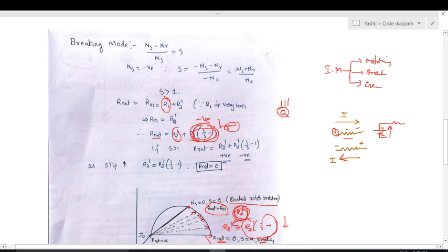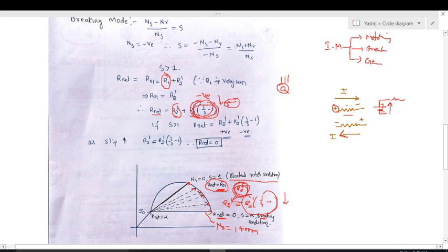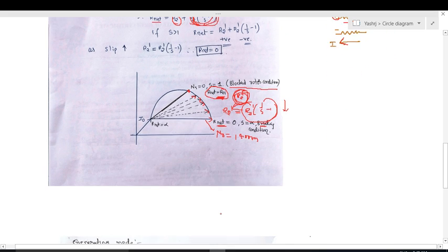As long as braking continues, the rotor speed reduces and the mechanical equivalent value reduces, because the slip also decreases, so the rotor comes to rest under block rotor condition. That's why under block rotor conditions, as we discussed earlier, the net resistance is equal to R01. So this is the behavior of the induction motor under braking mode.